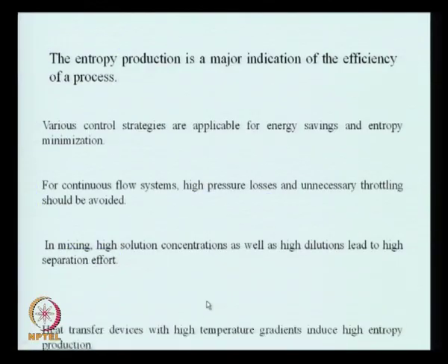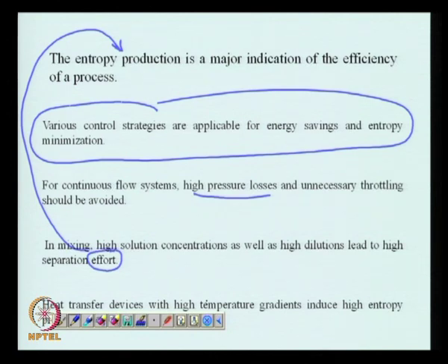So, that is what I would like to conclude today. In any heat transfer device also, since it involves large gradients similar to large velocity gradients, the large temperature gradients will also give rise to higher entropy generation in microscale devices. That is the peculiarity of the process and the device that we have to be careful about.